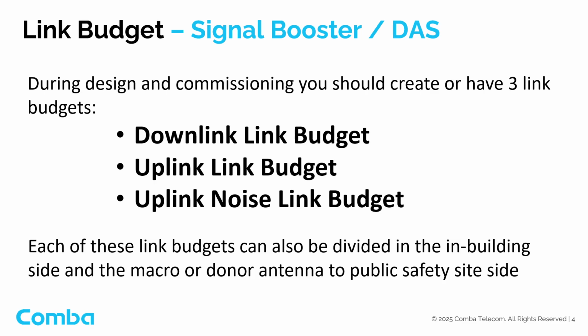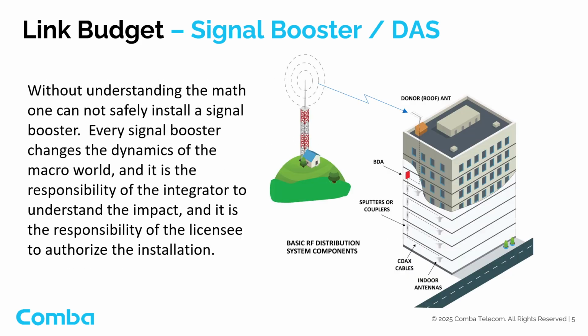Furthermore, link budgets are only estimations. During the installation and commissioning phase, real-life measurements are made and can be compared to the link budget estimation. Based on the comparison, final adjustments can be made to optimize the BDA settings and provide optimal coverage.